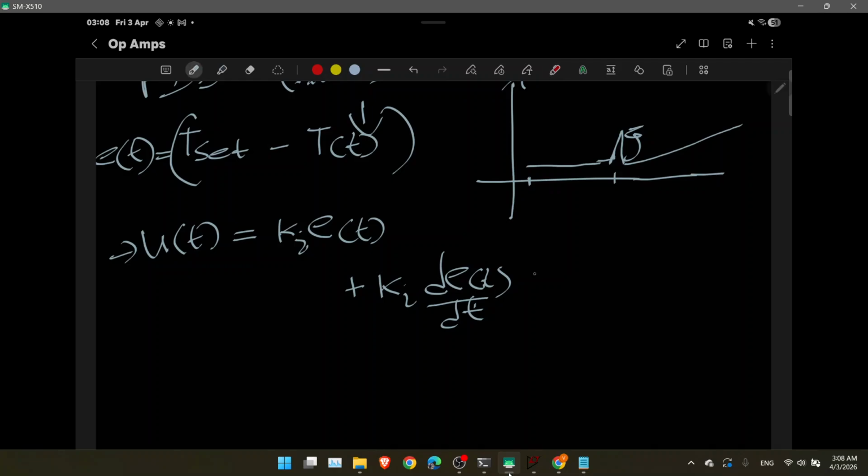What you should do is add integration of the error over time. So over time, if this becomes high, this can understand easily if there is a small deviation, a small error through a long period of time.